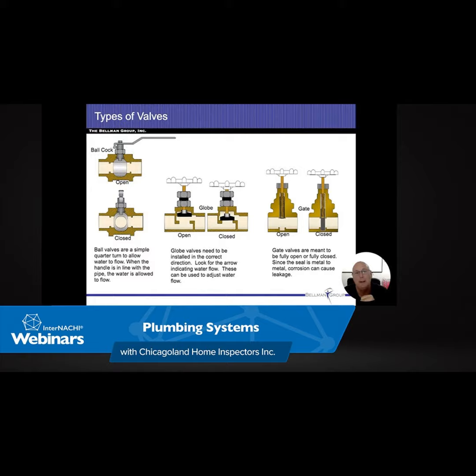Vent sizes when we come up to the roof. Typically, we don't want to see these 1.5-inch pipes or 2-inch pipes coming out through the roof line. They should be expanded to be about 3 inches. The only time you're going to see a narrow one is going to be a pre-World War II home, and it'll be for the kitchen sink area only. So it's just a waste vent or an air vent for a waste pipe. So there's only water that's going in there.